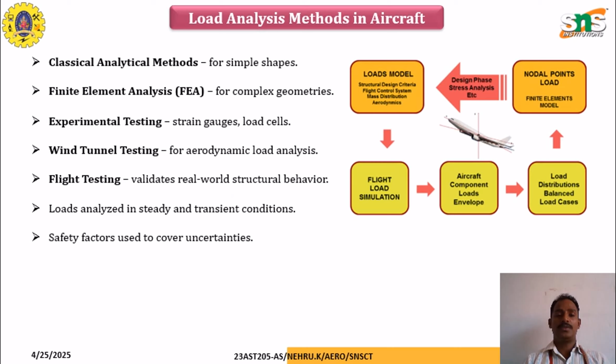Now coming to the load analysis methods in aircraft, we have a few: the classical analytical method, the finite element method, experimental testing, wind tunnel testing, and flight testing. The classical analytical method is used for the calculations of simple shapes and deformation, whereas FEM is used for complex geometry. Experimental tests with strain gauges and load cells are used to understand the loading pattern. Wind tunnel tests estimate the aerodynamic loads on different aerofoils, wings, and fuselage configurations. Flight testing validates the real-world structural behavior of the aircraft.